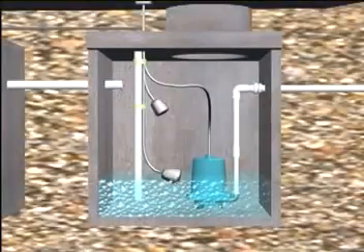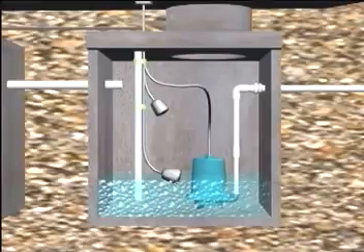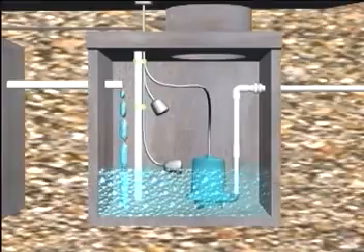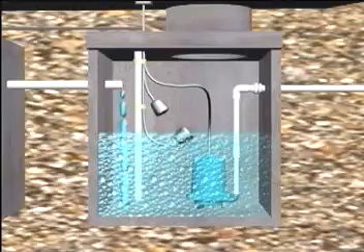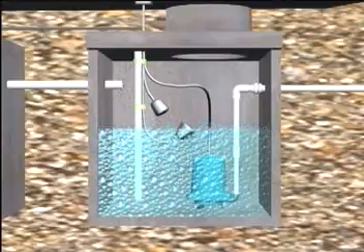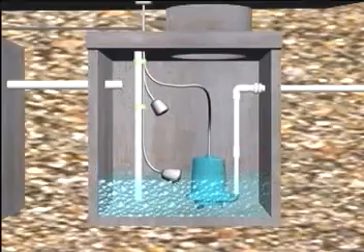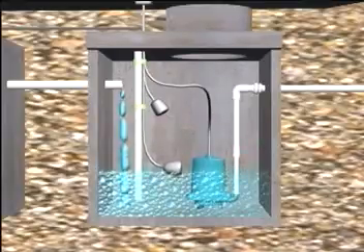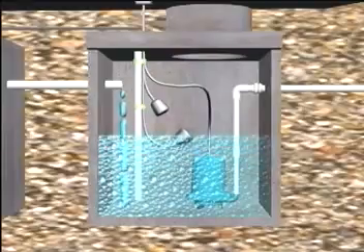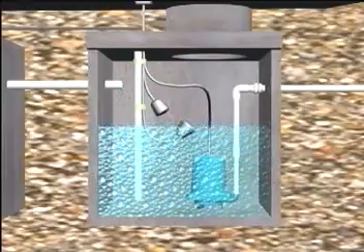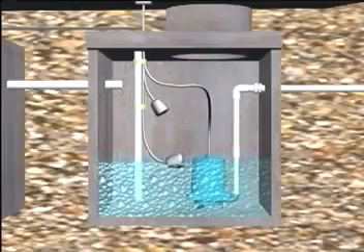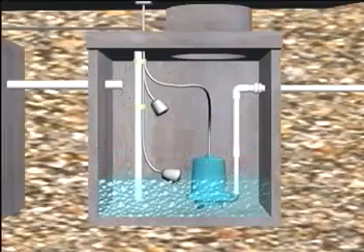Controls to regulate the on-off pumping cycles are essential to every wastewater treatment system. These can range from a simple single switch to a complex panel, depending on specific application needs, and are generally divided into two broad categories: demand and timed pumping. With demand pumping cycles, wastewater flows into the receiver basin, and as the basin begins to fill, a switch floats up and turns on the pump. As the pump empties liquid from the basin, the fluid level falls until the switch turns the pump off.